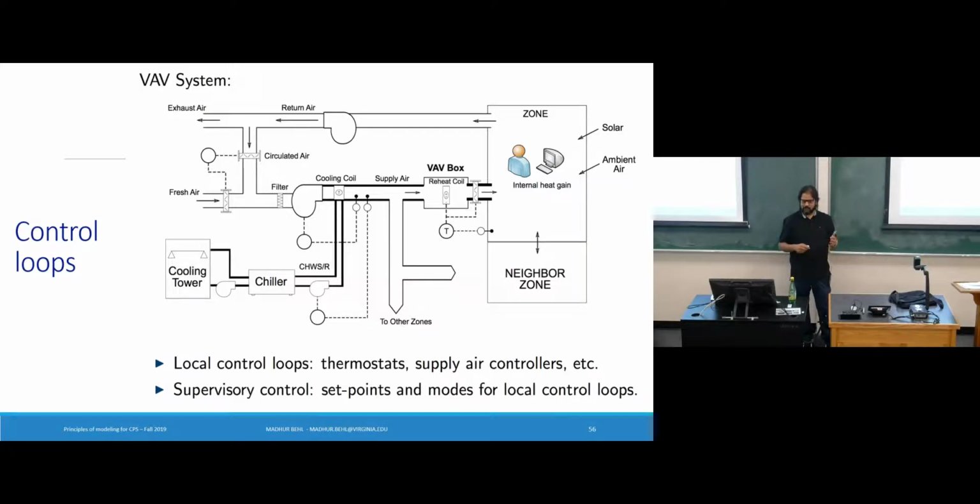And the degree of automation is because of many, many small control loops throughout this system. Okay, so let me tell you about some of these control loops. At a zone level, I told you there's a terminal unit which has 2 options. It has the option of opening the valve into the zone so it can adjust airflow, or it can also locally reheat the air at 55 to adjust the temperature of the air being sent into the zone.